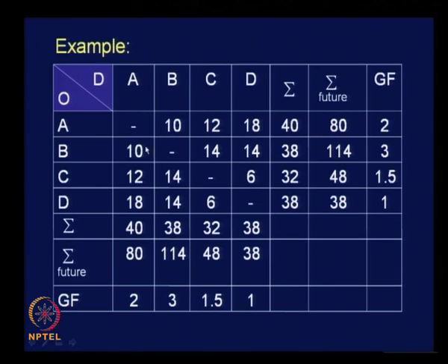Clear. Base year trip interchange is known to us, origin destination information is known to us, and base year trip production or trip origins and trip destinations are known to us for each of the zones. And we predict the trip origins and trip destinations for the horizon year also using the trip production model. So, we get these numbers readily available before we do the trip distribution process. Using these numbers we get the growth factor values. What is the next step?